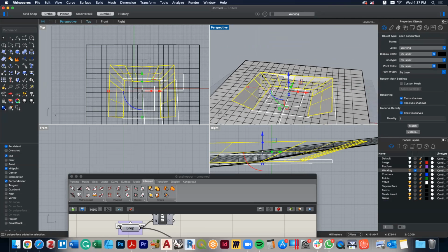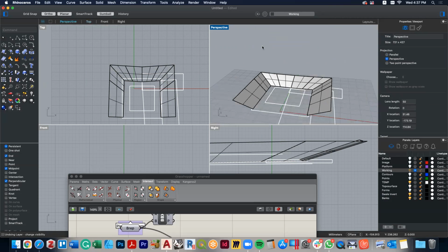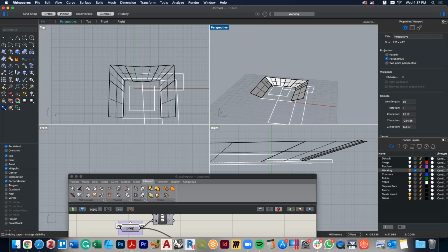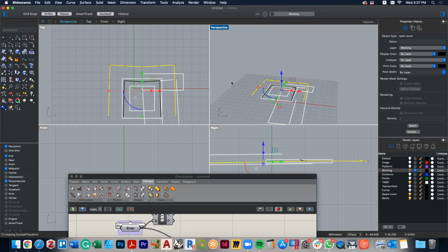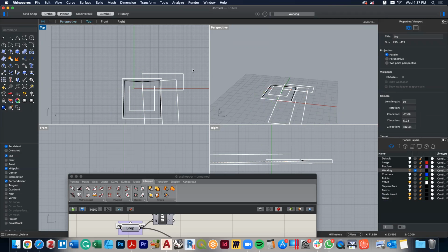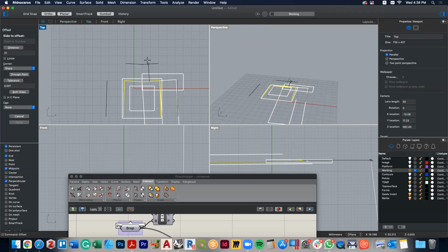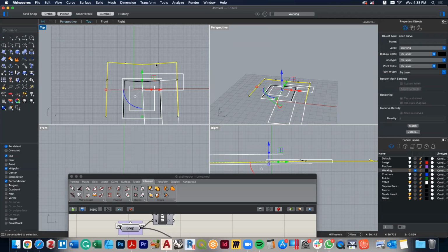Gee. So I'm going to do that again. So I'm going to undo, and I'm actually going to undo again. So I went to 18, now I'm going to go 21. This is a moment where Grasshopper would really help. So I go to offset 21, oops, offset 21. I choose this curve, offset it to there.